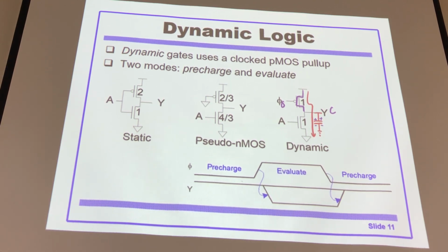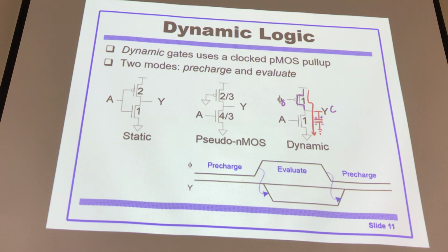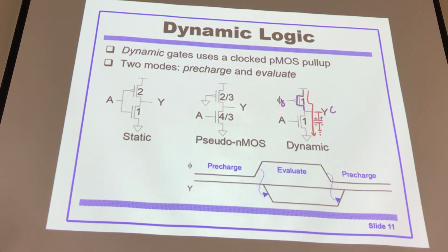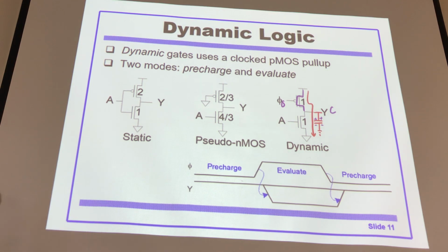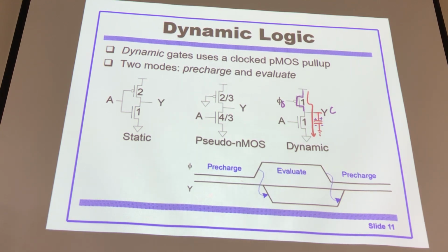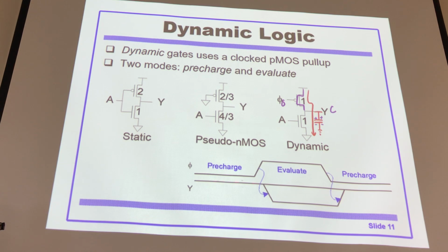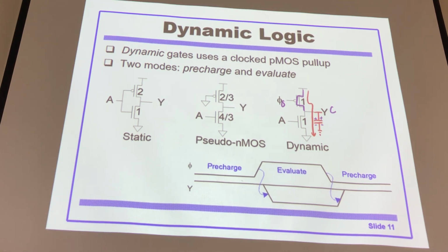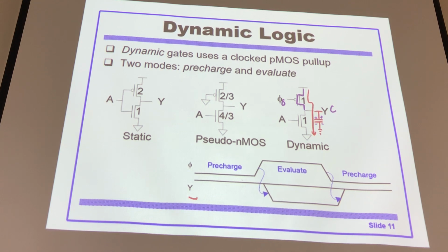There's a path which has a current going through. And that current will be charging the capacitor to accumulate more and more electron and hole on the capacitor. So this voltage will become higher and higher, eventually reaching high voltage here. At the beginning it is quicker, but then slower and slower.